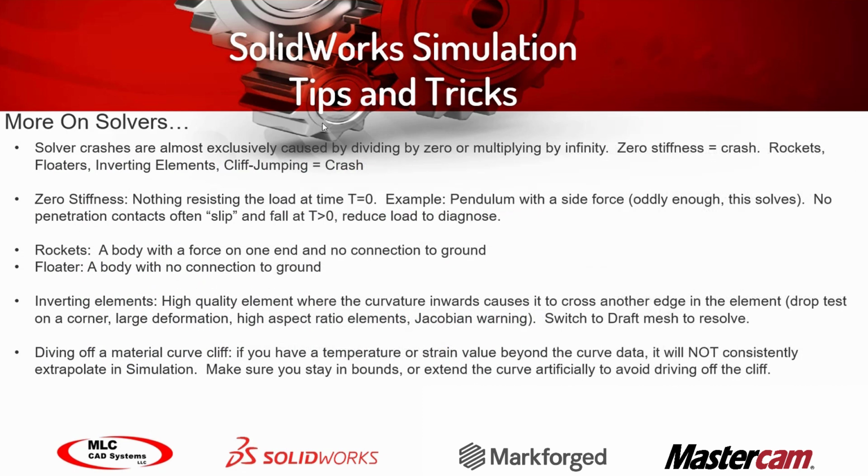A couple of tips and tricks. I had mentioned a few to try and troubleshoot why a study may not solve. Maybe you don't have adequate fixtures. Maybe you don't have the correct contact set, so components are flying off one another. The elements, of course, may be diving off a material cliff. Sometimes it'll fail and say the solver failed. It may be going beyond the scope of what the mechanical properties in the material definition allow for. So that's typically something we see in custom materials more.